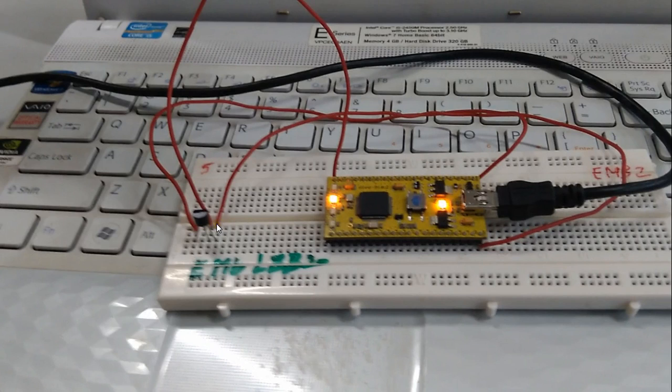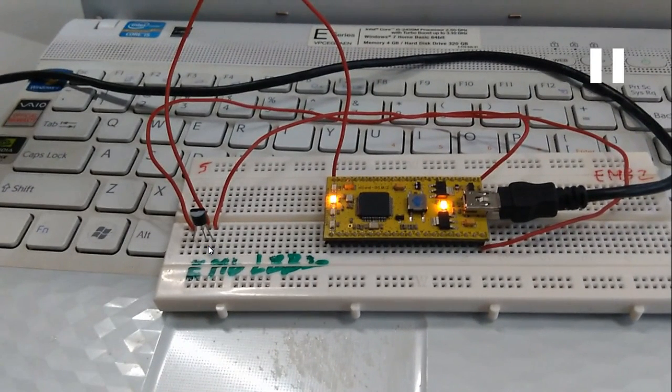In the temperature sensor there are 3 legs, which include one VCC, one ground, and the analog output. The middle pin of the LM35 temperature sensor gives the analog output. That will be connected to pin 20, and VCC and ground will be given, and this program will be coded and dumped in the mbed board, and the USB will be connected to the Tera Term serial monitor window.